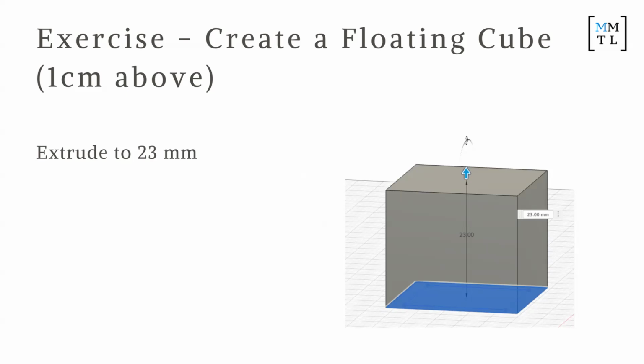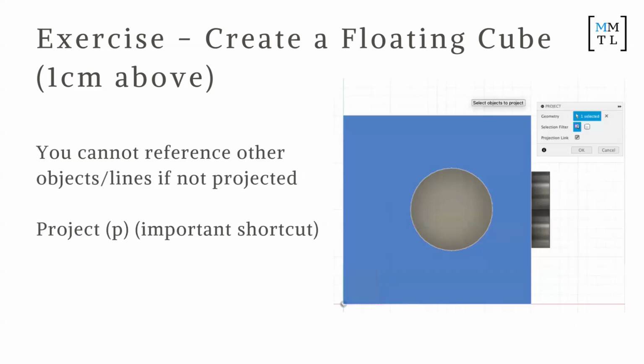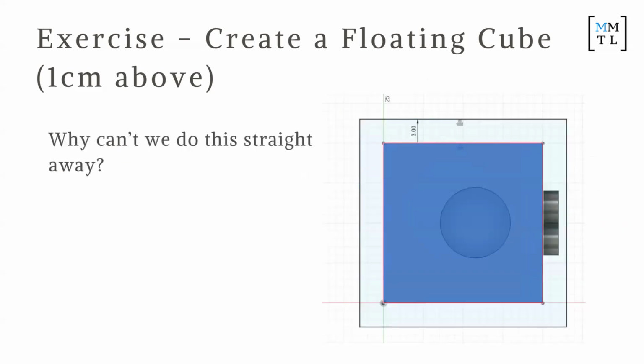So you want to understand. We want to make it 3 millimeters bigger. So offset that. Select the edge, and then 3 the other way. So -3. Good. Nice, now we've got a closed profile, it's shaded blue. And then finish the sketch.